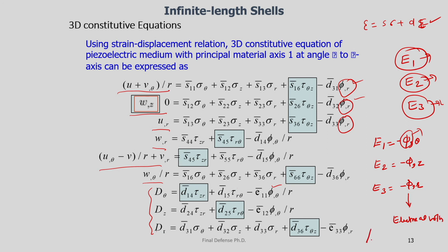Basically, if we talk in a discrete sense, because we have written in vector form, it will be V by H, meaning the voltage across the thickness. Phi comma z, if we write it as derivative, is d phi by dz: a small change in voltage upon a small change in thickness. So the voltage across the thickness gives you the electrical field in that direction.